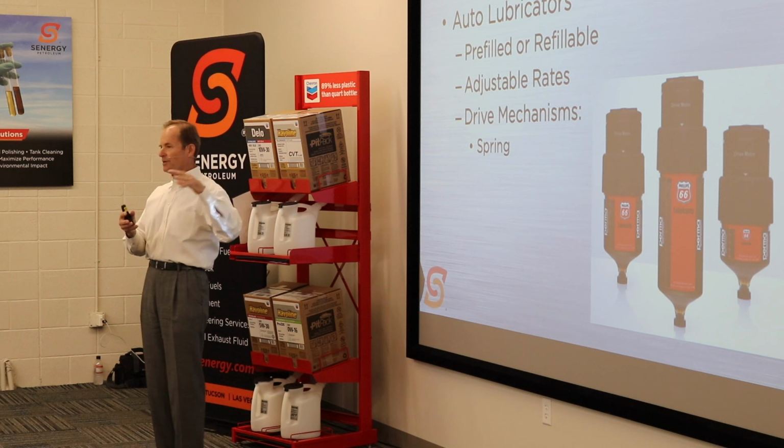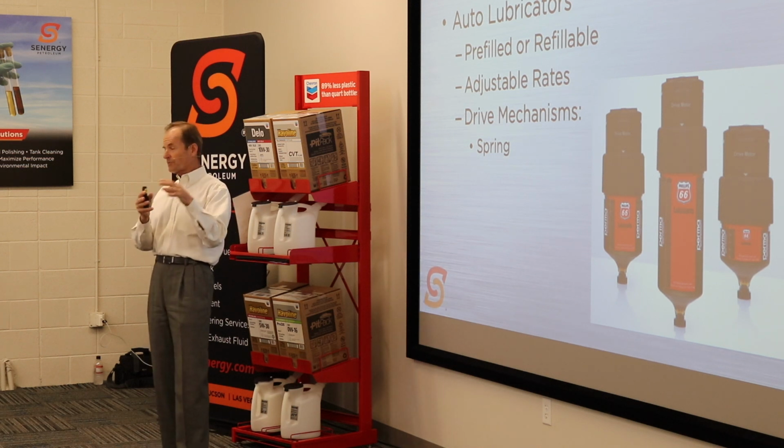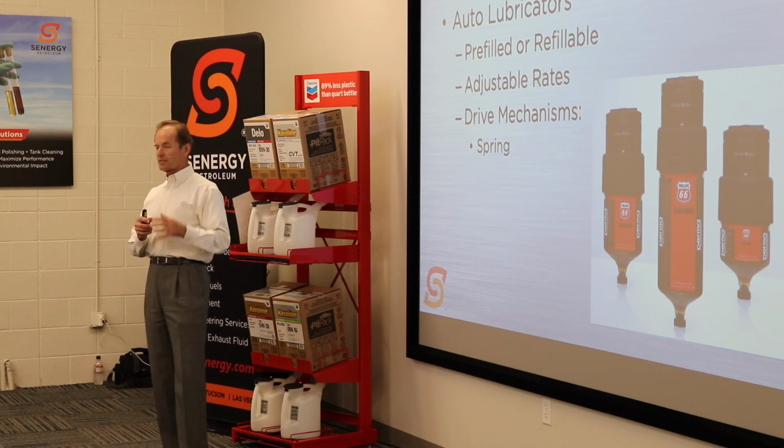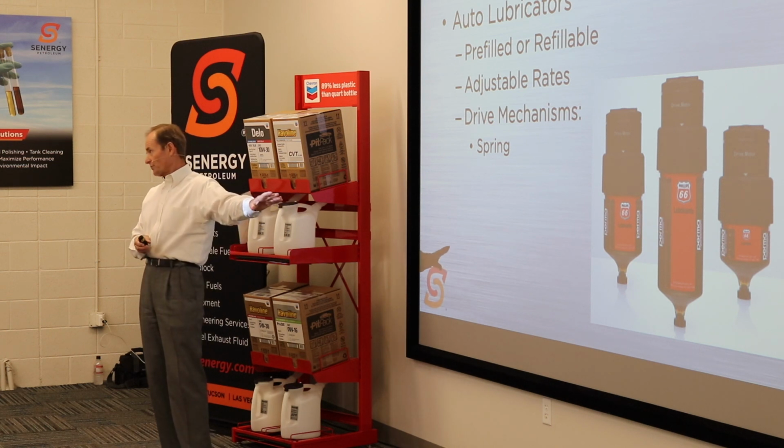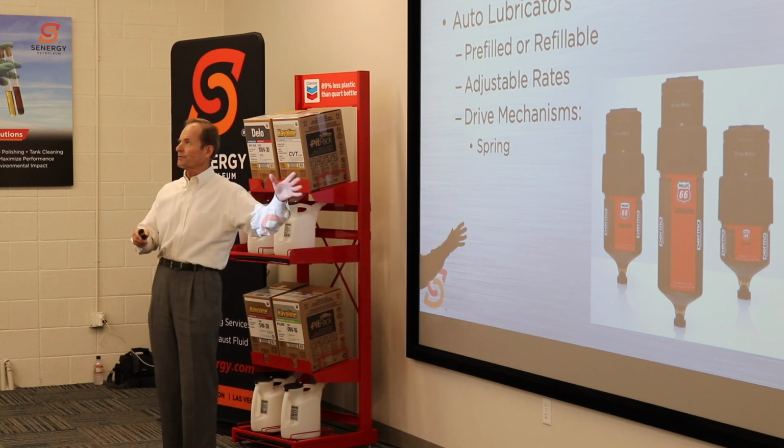And constant pressure on a grease will work to separate the oil from the thickener. So that's sometimes a problem, depending on the rate of grease you're using and the quality of the grease you're using, that sort of thing.